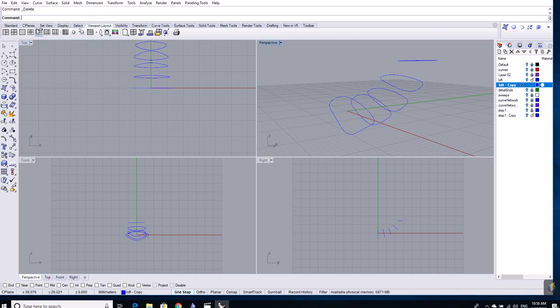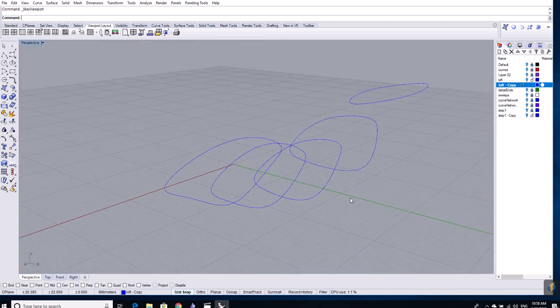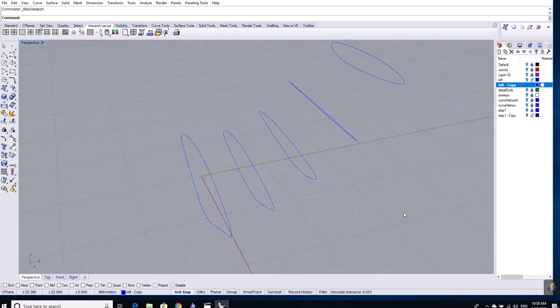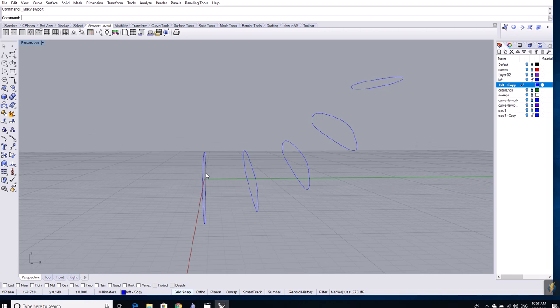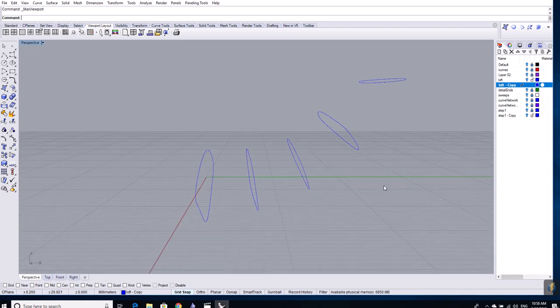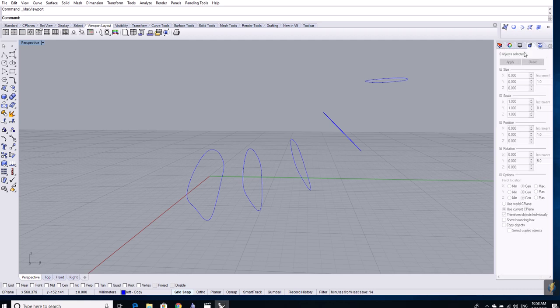I've got these closed shapes that I made, kind of an oval shaped thing. And the way that I made them was that I turned on the control points and I just cut and paste a whole bunch of them and edited them. And then I moved them, and then I changed the rotation using the box edit tool. I just rotated them. And when I use Loft on this, it's going to create one form. These are all like cross-section pieces that it's going to form together.